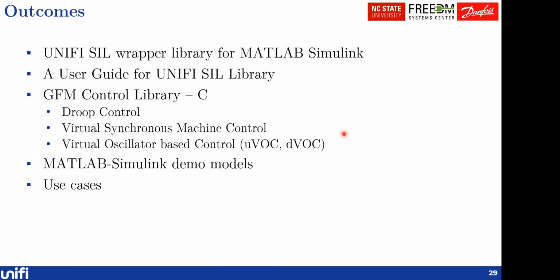Then we also made a grid forming control code base, which gives you the option to use droop control, VSM, or virtual oscillator based control, UVC or DVOC. We created a bunch of demo models that show how you can use both this library and code base together. And we also showed some use cases, how you can use it in different applications.